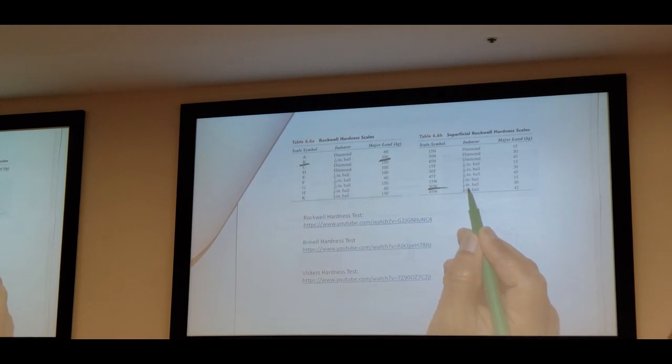It is a 1/8 inch ball, and the major load is 30 kilogram. That's how we can determine it.